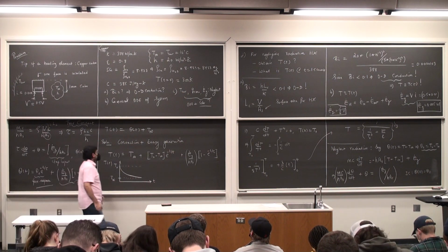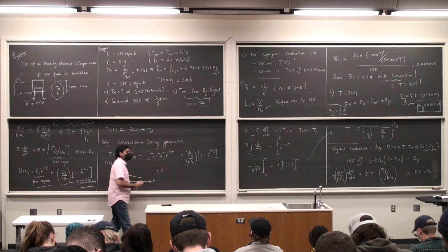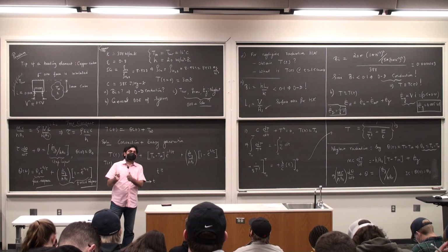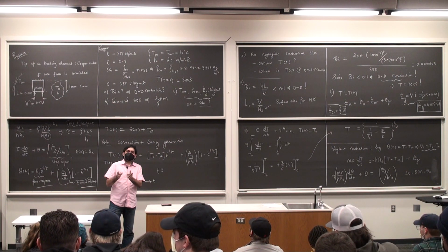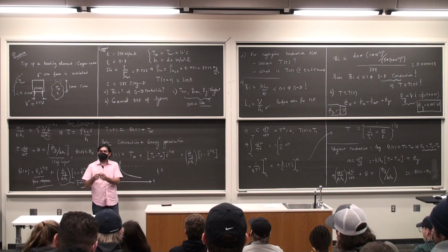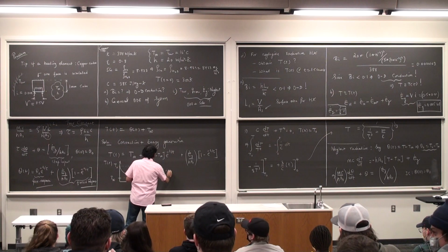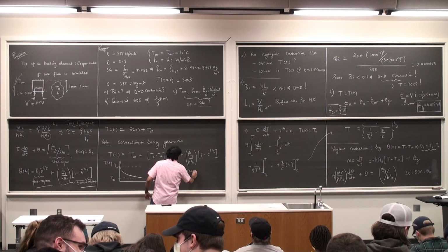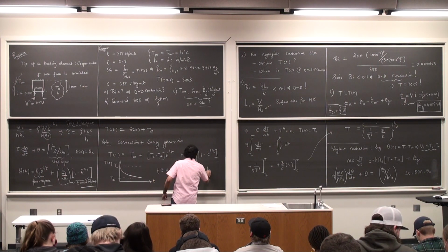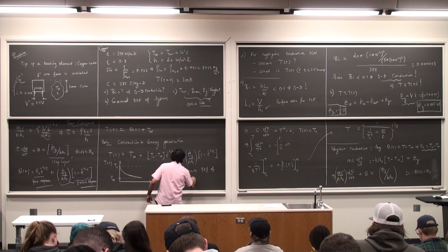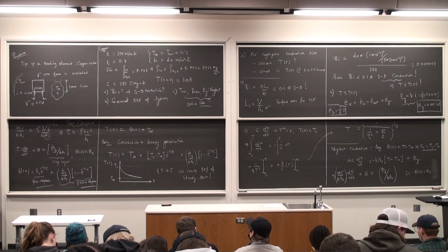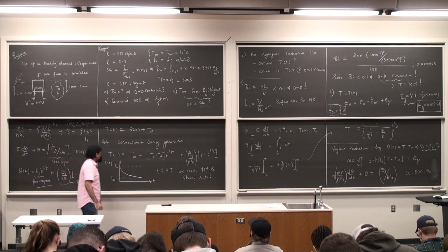And when time t is approximately, does anybody from system dynamics remember what is the time it takes to reach approximately steady state? Any other answer? Any other answer? Yes? Is it 4? 4 tau. We reach up to approximately 98% of steady state. Okay? If the initial temperature is lower, then the curve will just be a mirror image of it, whatever is drawn here.